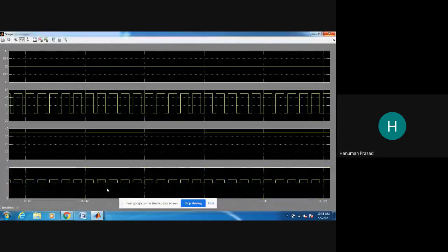This is your pulse. The top portion is the input voltage, 50 volt, always fixed. This is the output voltage that you read about in the book. This is the filtered output voltage. Filter means pure DC. This is pulsating as a pulse due to the pulse generator, which is the output voltage as a pulse that you draw in the book. And you are finally getting the DC output after the filter, 35 volt, and this is the pulse generator pulse.